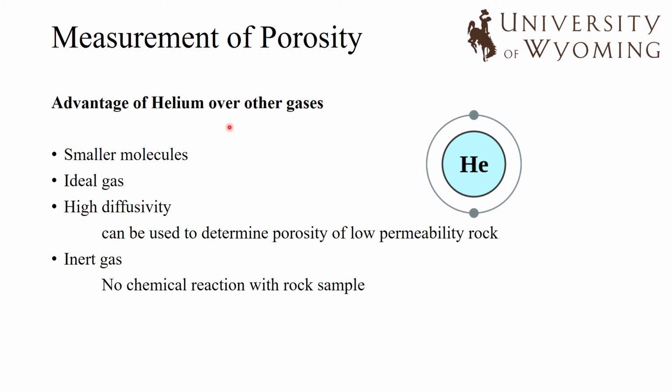Generally, using helium over other gases is advantageous because helium has smaller molecules and also high diffusivity, so it can go into very small pores that other gases may not be able to go into, and therefore it can measure the porosity very accurately compared to other gases. Also, it's an inert gas, so it's not going to react with my rock sample.